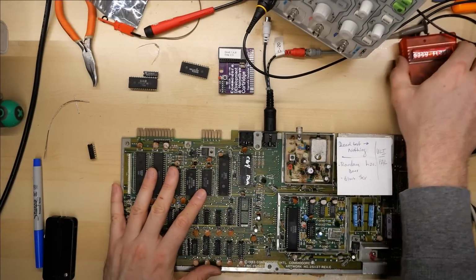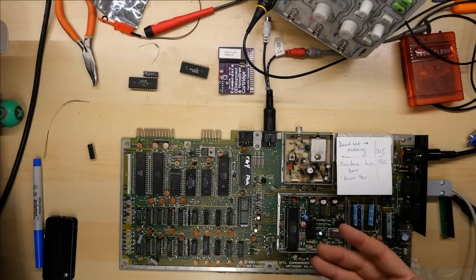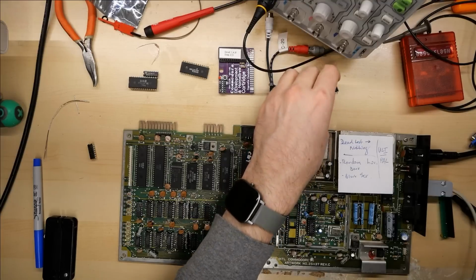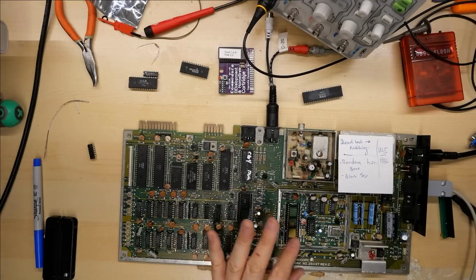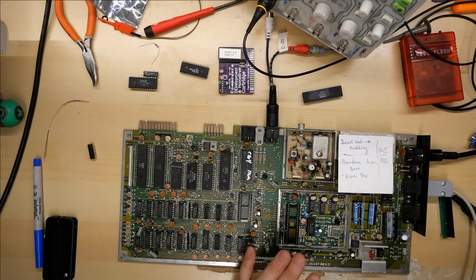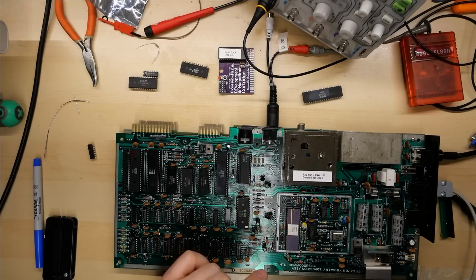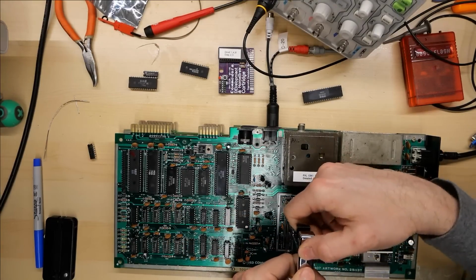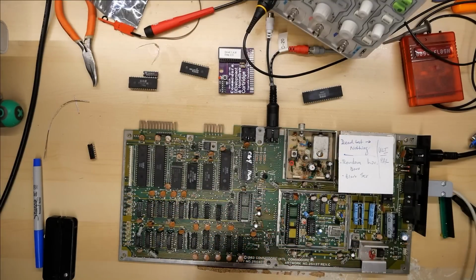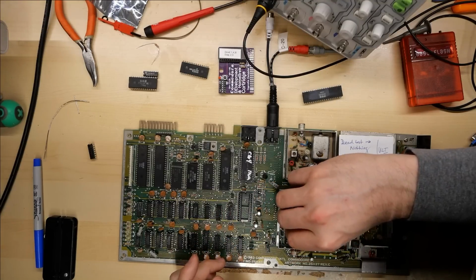But a game like Galencia can actually work without fault. So a real mystery. Before I do the final desoldering of the CPU, why don't I take the VIC out? Since it's in a socket, it only takes me a second to swap this out with the one from the other PAL board I just had out a second ago. Let's just make sure that that is not causing an issue. We know that the VIC chip interacts with the RAM, right? We've already established that in part 1. So I'm going to put this R1 chip onto the other board and we'll just see if that problem goes away. I'd say there's pretty much no chance that this is going to fix it, but I might as well try it, because it is possible. And since this won't take any effort, just plugging a chip in here, may as well do it.